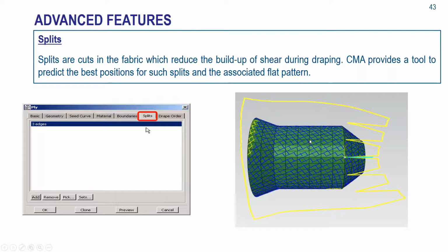You can imagine when we're approaching Christmas and we try to wrap packages, it's not always easy if there is anything other than a box that you are wrapping. So for these purposes, as one of the more advanced tools, we can also predict where we need to make splits or basically cut this initially in order to avoid undesired wrinkles in a structure.